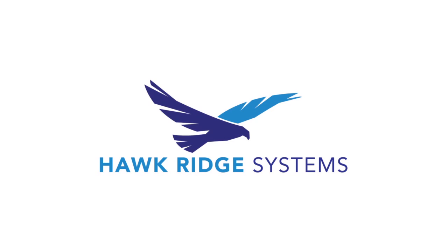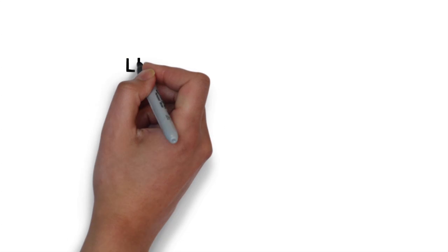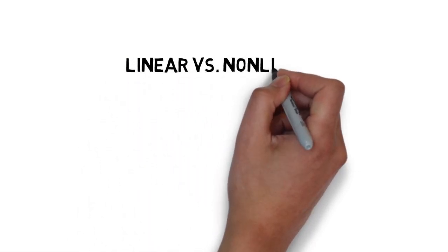In this series, we'll take a look at various engineering concepts and how they relate to analysis in SolidWorks. In this video, I want to talk about linear versus nonlinear analysis. One of the key assumptions we make for many simulation studies is that our analysis is linear. I want to go into some detail on when this assumption is valid and when it's not.